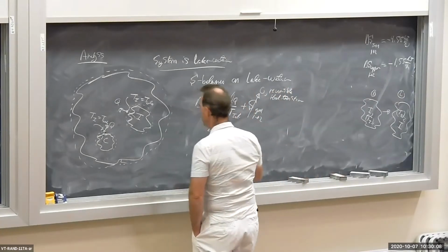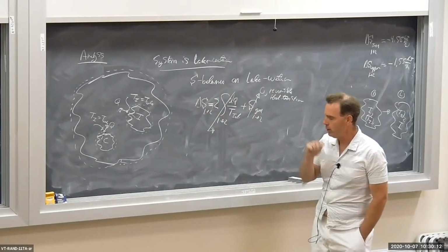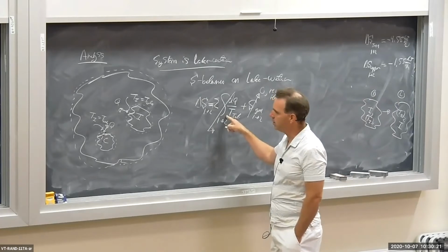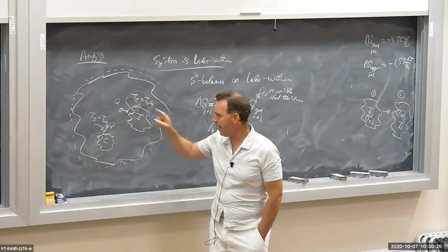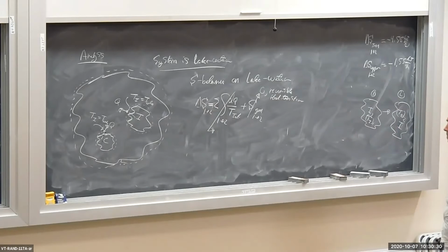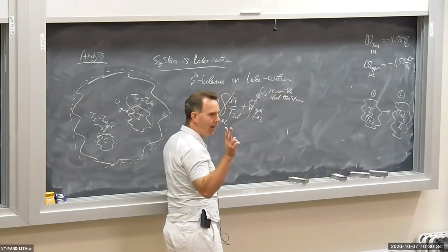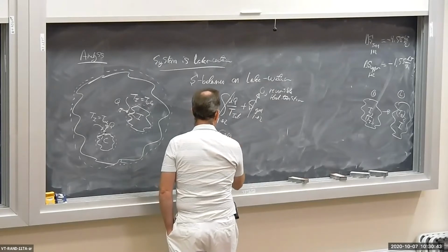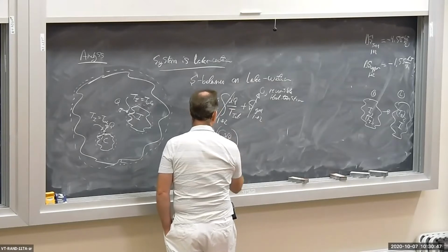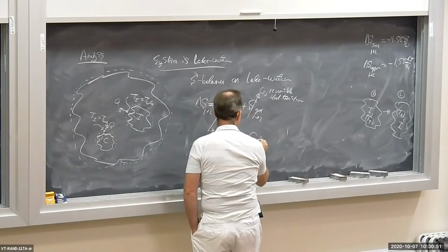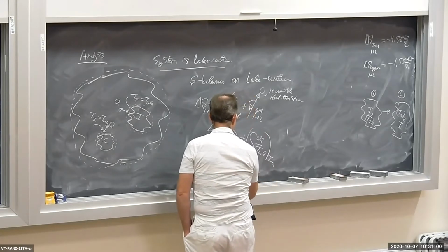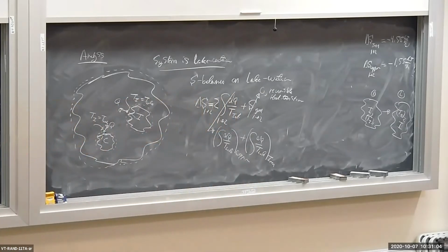Let's see here. There's actually two heat interactions going on. There's one going on with the copper and the iron. So two heat interactions. So this integral becomes two integrals, integrating the heat transfer from the copper to the lake and the heat transfer of the iron to the lake. The interaction temperatures are always T lake. So this is equal to the integral of del Q over T lake, and that's for the copper, plus the integral of del Q over T lake, and that's for the iron. Two heat interactions, therefore we have two integrals. Interaction temperatures are the lake temperatures.